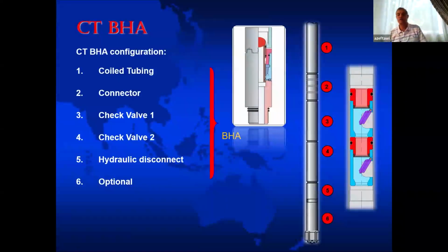At the bottom of the coil, we put what we call the BHA, bottom hole assembly. The first piece of the bottom hole assembly we use is this one. This one we call the connector. In particular, this is what we call an internal connector or roll-on connector. Why is it an internal connector? Because if this is the end of my pipe, it goes inside it like that. See, it goes inside. We connect it like that. And how do we connect it together?